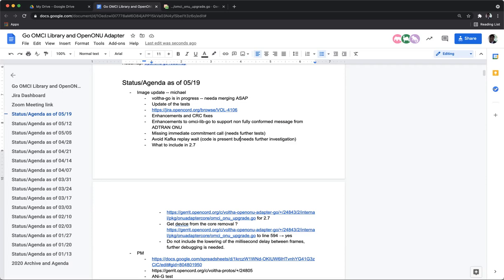If you send a message that requires a reply, you actually need to wait for the OMCI reply to come back in for that message or a timeout. Because I think at least the CIG microplug ONU and a few others might actually overrun if you send messages without following the stop and wait protocol. Yeah, so might be that is also worth some consideration.